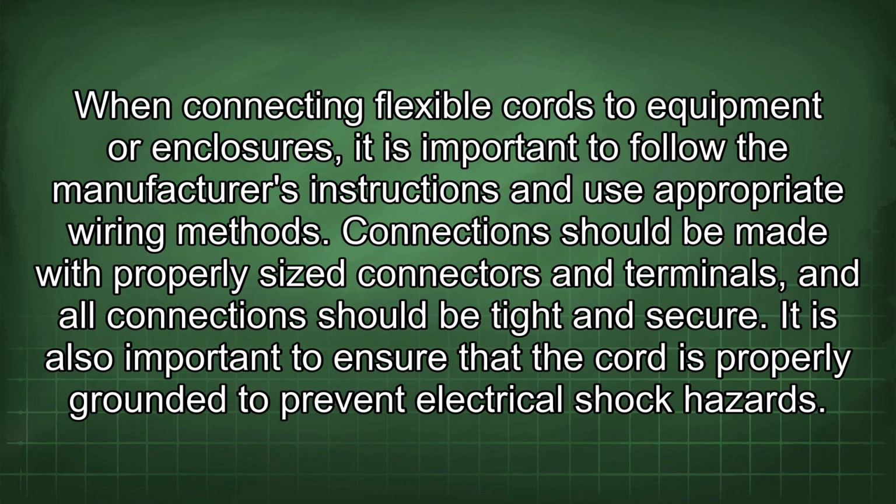When connecting flexible cords to equipment or enclosures, it is important to follow the manufacturer's instructions and use appropriate wiring methods. Connections should be made with properly sized connectors and terminals, and all connections should be tight and secure. It is also important to ensure that the cord is properly grounded to prevent electrical shock hazards.